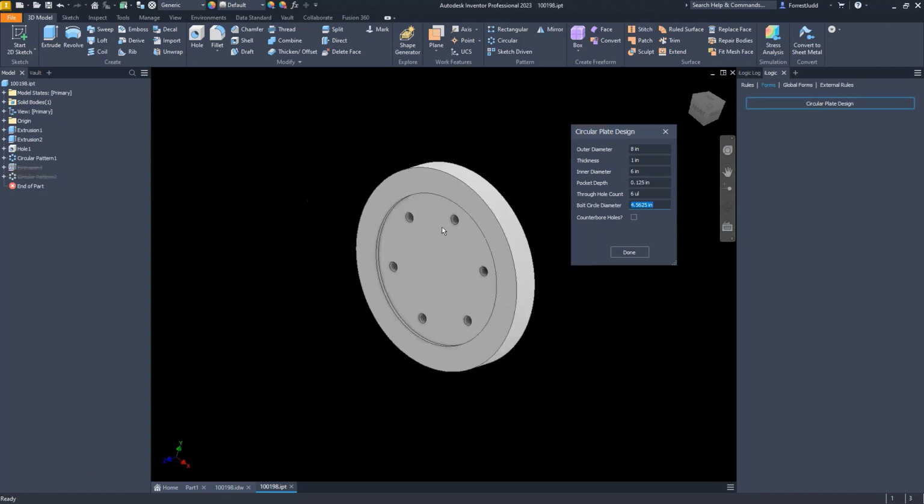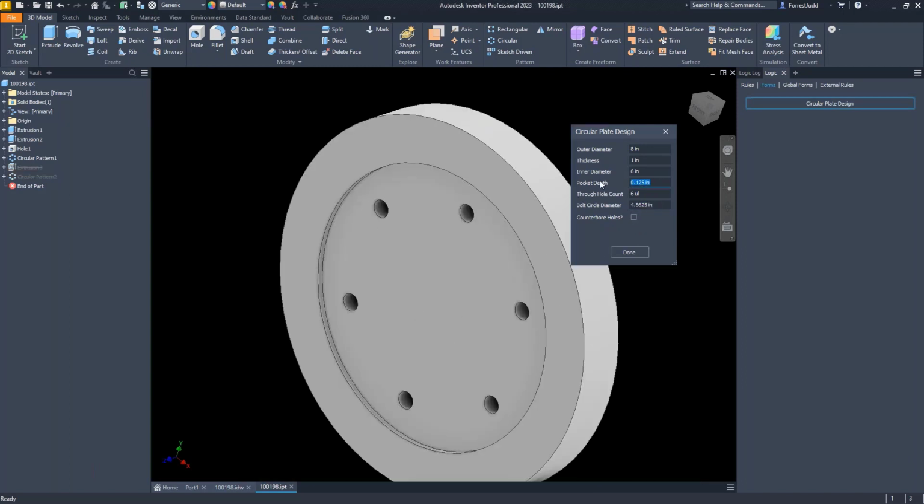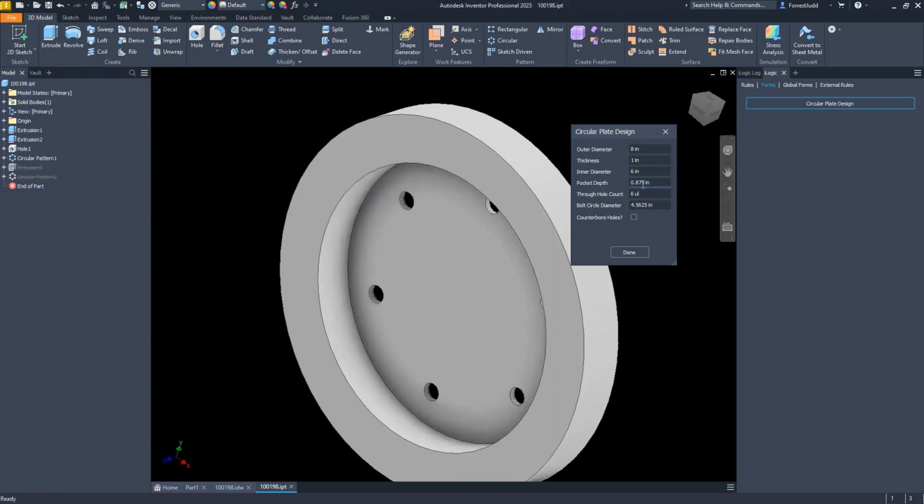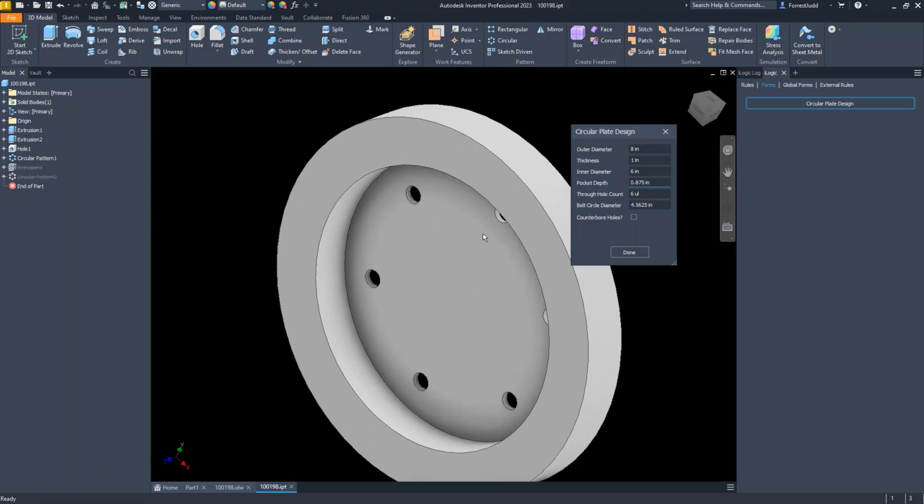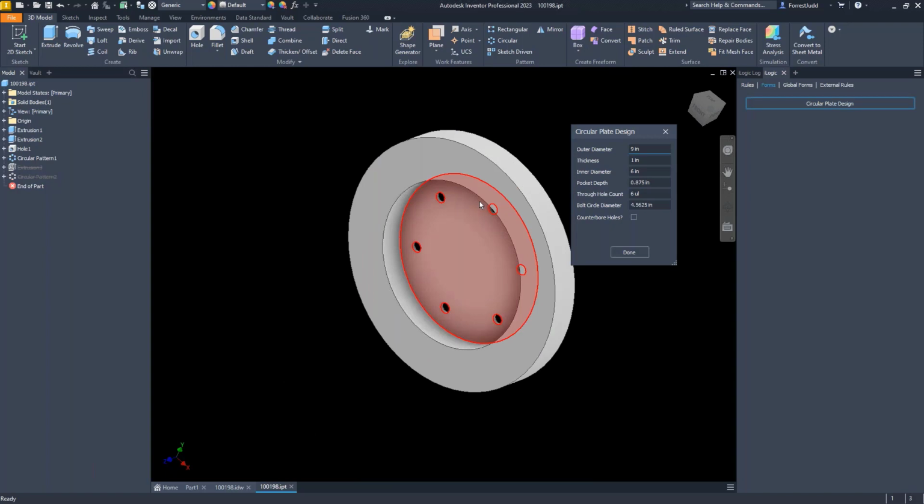So if I were to say the thickness of this should be like 10, that's completely invalid. If I did that without iLogic, it would break the model. It would cut through and I'd have a bunch of errors over here. With iLogic, it's like, no, okay, I'll give you this much. You can have this much. So I don't need to know how this model works. I can just put in the numbers that I need, and I'm going to get what I get.